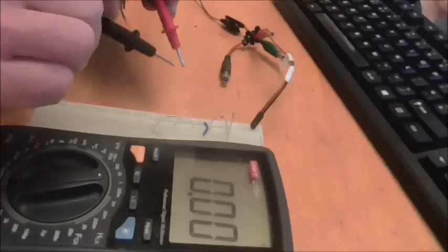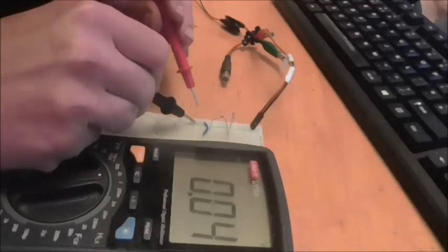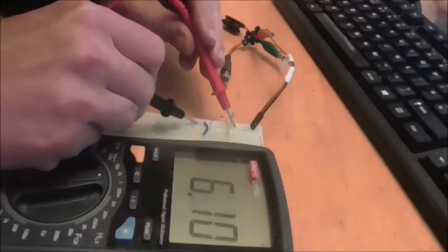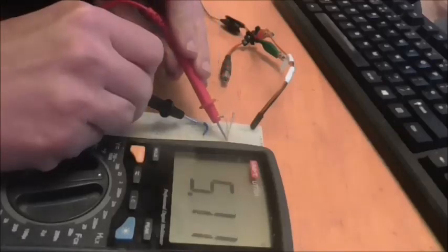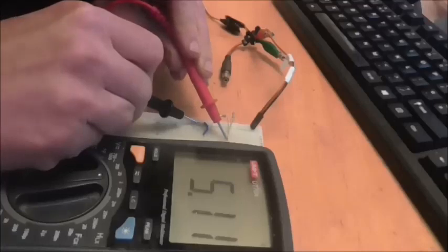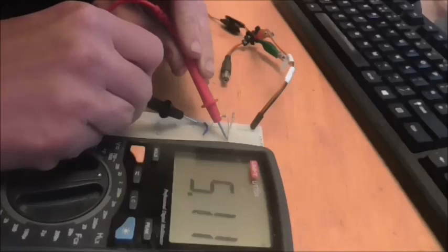Let's make sure we've got 6 volts there. Just slightly over, and let's see what we get here. Didn't drop out. Well, it's soldiering on. So we've had 3 different incoming voltages, and the difference between them has been about 3 volts. But the outgoing voltage from the Zener diode has always been from 5.11 to 5.15, so we get a remarkably stable voltage there.